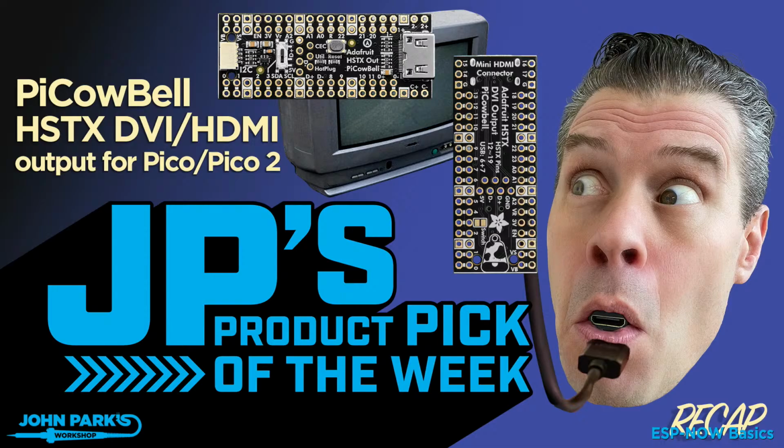This week it was this PyCowBell, the HSTX DVI output. Here's a little recap. It is the HSTX DVI PyCowBell for Pico and Pico 2. It works best with Pico 2, RP2350, gives us speed, gives us RAM, and gives us dedicated pins for the HSTX peripheral that we can use to send video out over that mini HDMI connector.